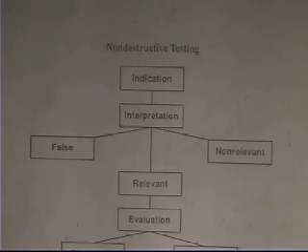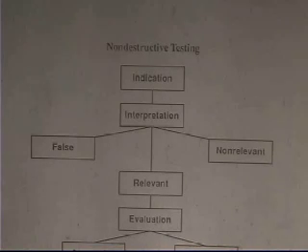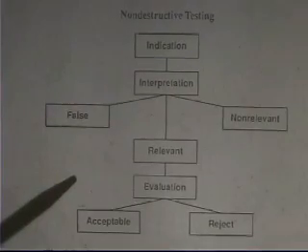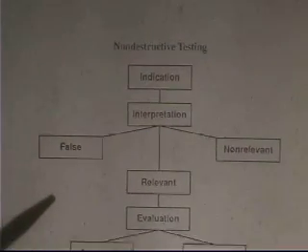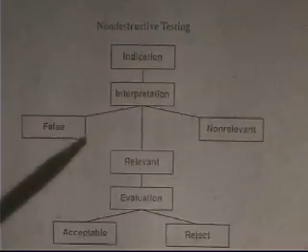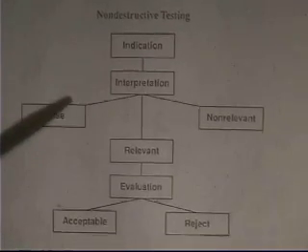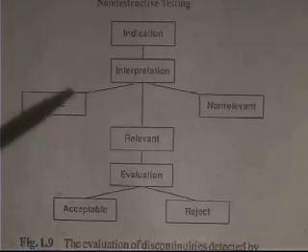Okay, a lot of times people say, well, inspect it per such and such, and a standard code that's been around for a while will have objective criteria for acceptance and rejection. Sometimes when someone doesn't call out a code, but they call out some inspection technique without calling out a code, they'll say, well, use magnetic particle inspection. Okay, I can get an indication. Now how do I decide whether to accept it or reject it unless you give me a criteria? What size flaw is rejectable? Okay. So people sometimes forget, engineers sometimes forget to give an acceptance criterion.